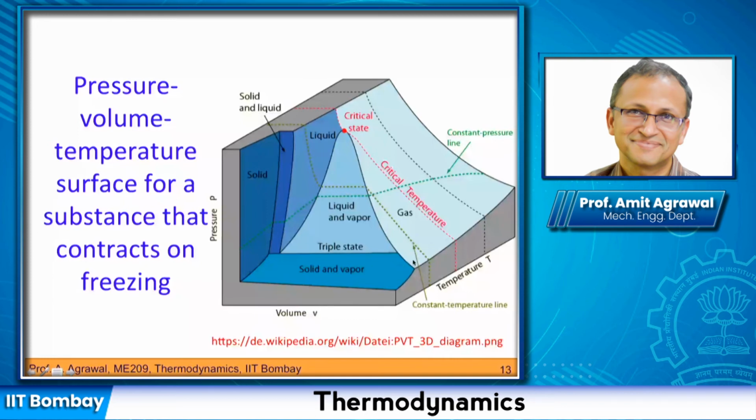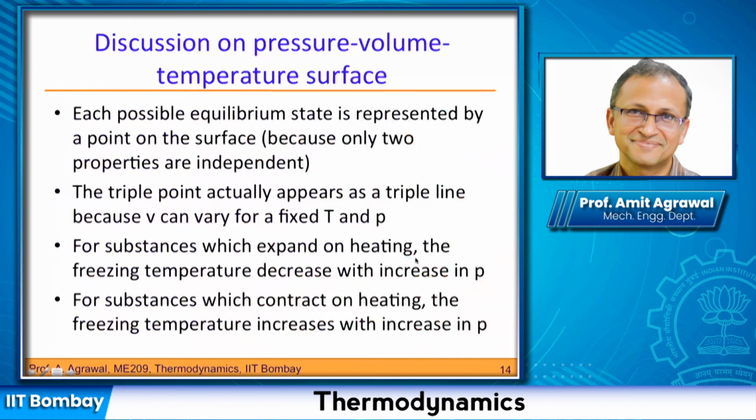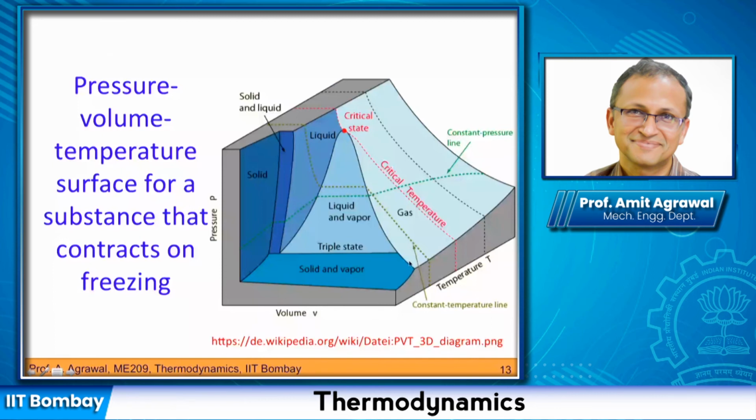Okay, at this pressure level, you start off at some point here. Okay, a point here, and then you keep reducing the temperature. You will see that you will now cross into this part. You will essentially start getting solid, and again you can have a quality parameter which will define how much solid versus how much vapor you have, and ultimately you will get to complete solid here. And this is your sublimation process.